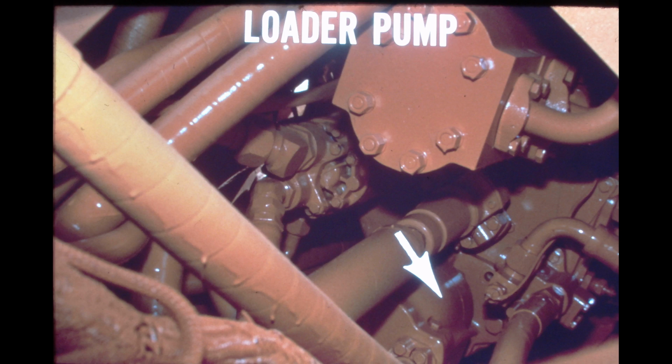The loader pump is a single-element gear-type pump which is driven off the torque converter. This pump provides oil flow to the main control valve whenever the engine is running. The pump is rated at 44 GPM at 2,500 engine RPM.